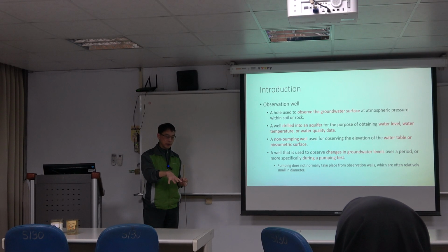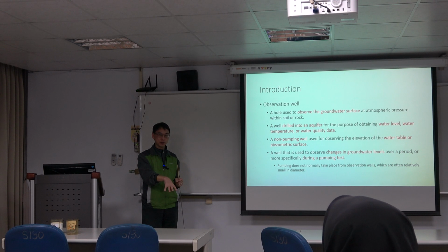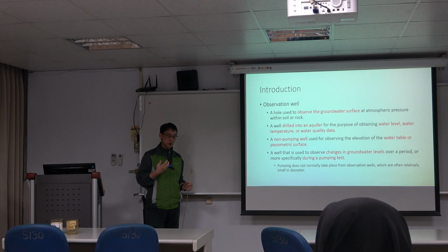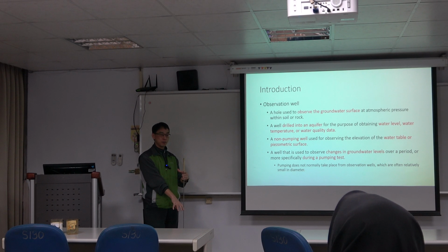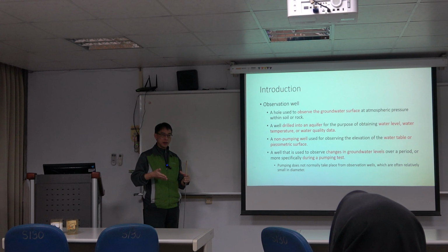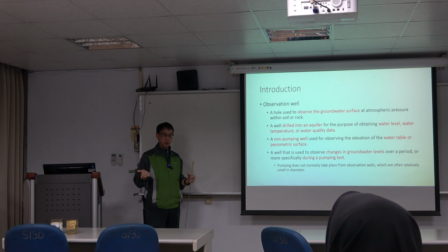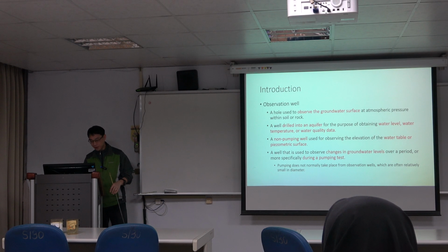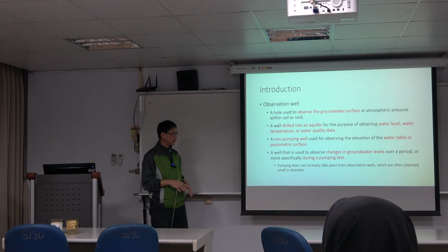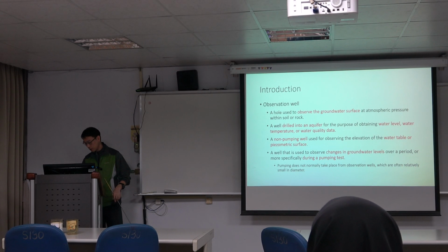Just to remind you, you need to be careful. For example, if you know the site has highly permeable materials like gravels or boulders, you need to use a larger-scale borehole and put a strong pump inside, and then you will be able to see the decline of the water levels, and then you can assess the T and S values. Otherwise you will meet problems. You need to spend much more money, and you might get fired by your boss, because you made a mistake. You cannot earn money like that. So, some experience to share with you.